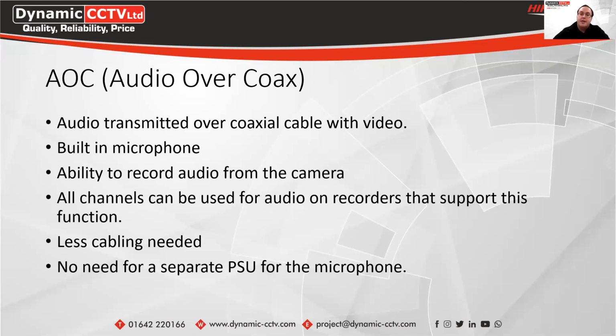You do still need to power the cameras with a separate PSU, but this gives you the benefit of having a built-in microphone in the camera itself and not having to run a separate power supply and a separate audio cable for the actual microphone. And with this, you can then use the system to just hear the live audio from the cameras with built-in microphones, or you can actually record the audio as well to the video stream that's recorded on the DVR itself. Depending on how it needs to be used in the scenario, you can mix and match depending on what's needed for the actual system itself.